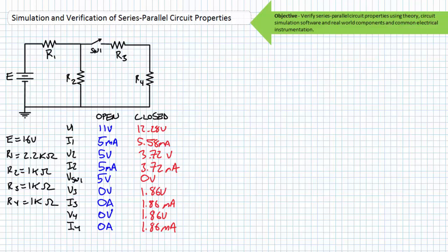The solution to this troubleshooting scenario is well within the reach of individuals with an understanding of basic series properties and Ohm's law. At its core is the fundamental understanding that if current is too high, it's because resistance is too low. With switch 1 open, this is a pure series circuit, and the current through both resistors should be the same.